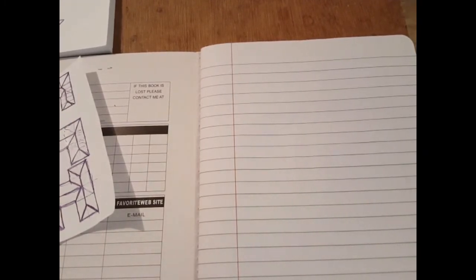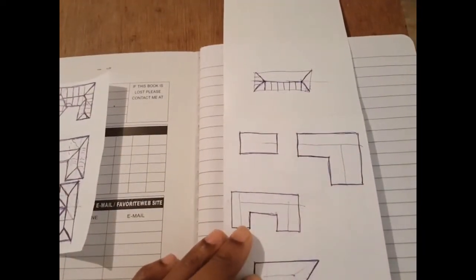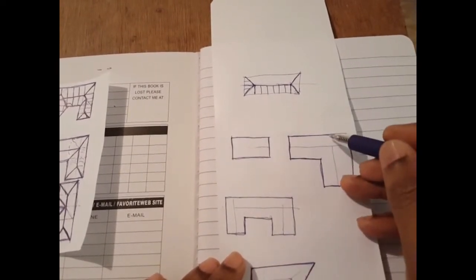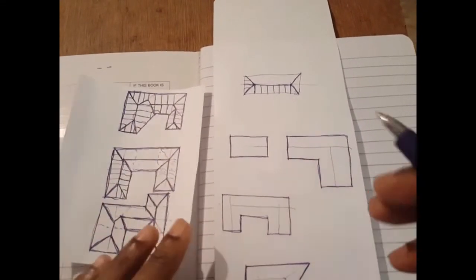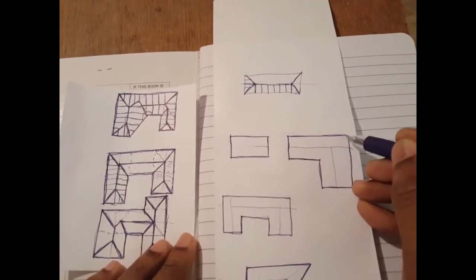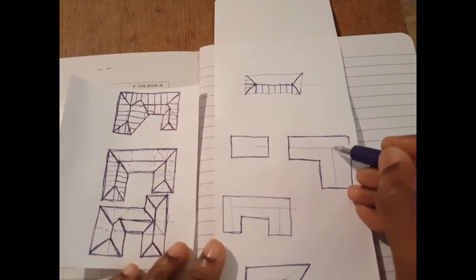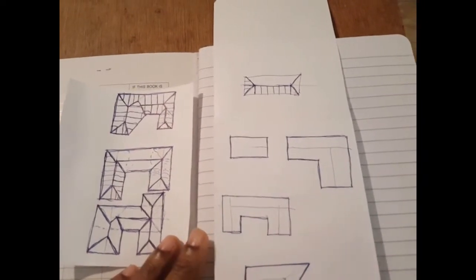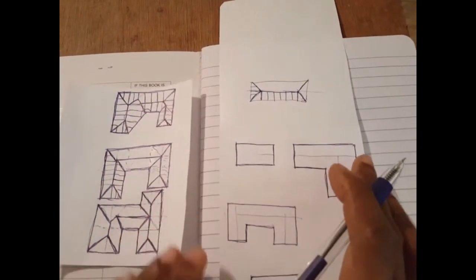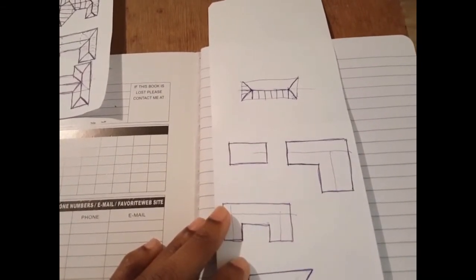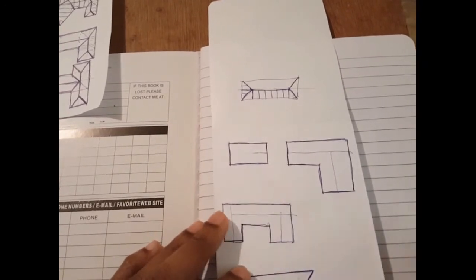So let us start creating these rules. All right. Another rule that we need to be mindful of is that every hip rafter must be generated from a corner, yeah, from one here, one there, one there, one here, and it must be at right angle. All right. So let us start with probably one of our most basic roof frameworks. All right. Let us start with this one.